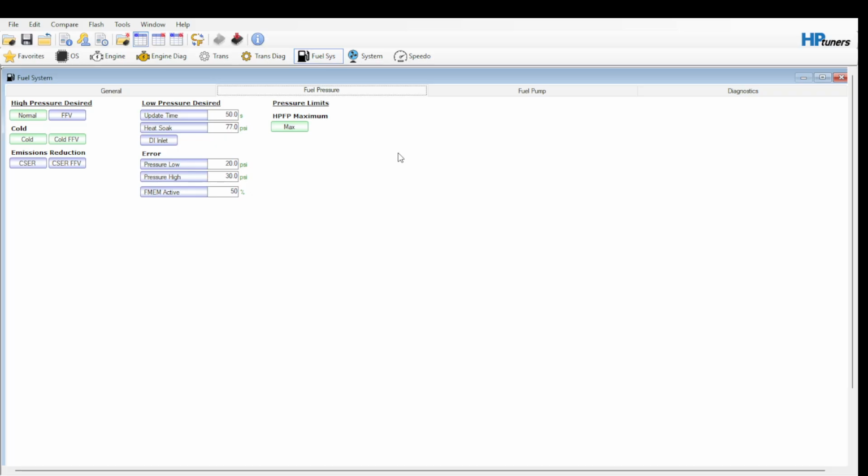But this goes back to another thing that I see time and time again. People like to say that you either need an upgraded high pressure fuel pump or that you need upgraded injectors. Now, just like you won't be able to see a more aggressive camshaft for the F150 because of the VCT system, you also aren't going to see very many injectors that are legitimate options for you as an F150.